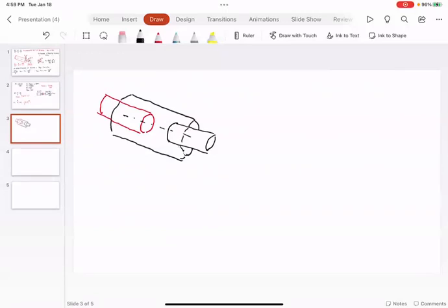Have you used the 3D printers in the Innovation Hub? If you go and see the 3D printers, there is a stepper motor. At the end of the stepper motor, there is a lead screw. And the stepper motor and the lead screw are connected with a sleeve coupling. This is the basic type of coupling that is used in power transmission.